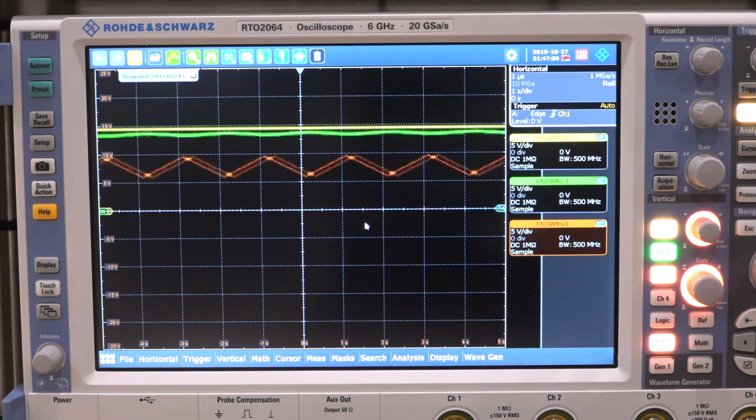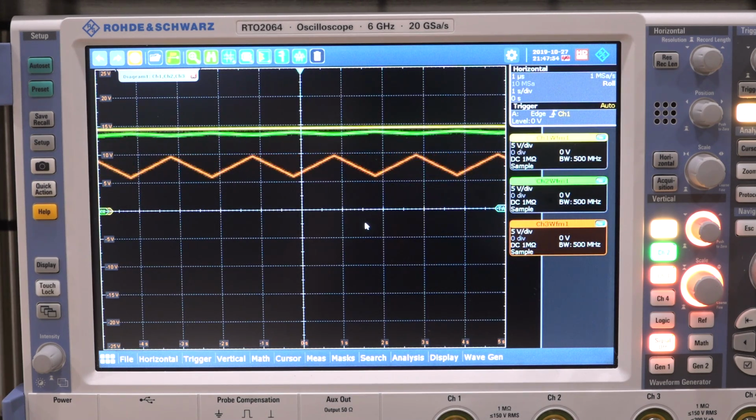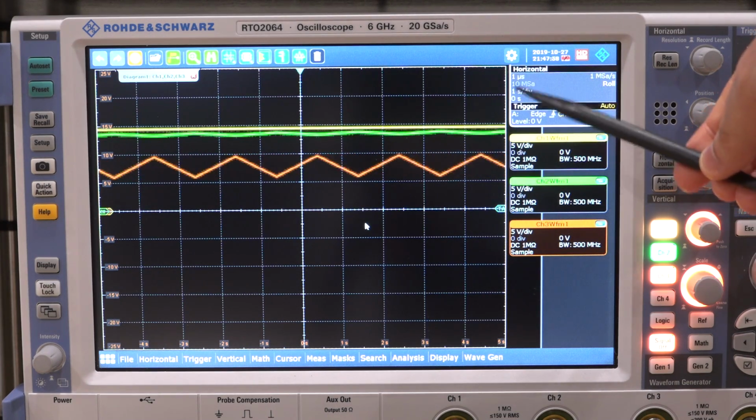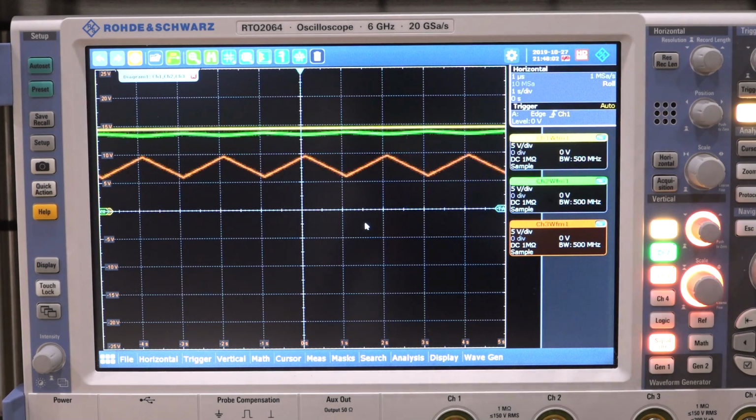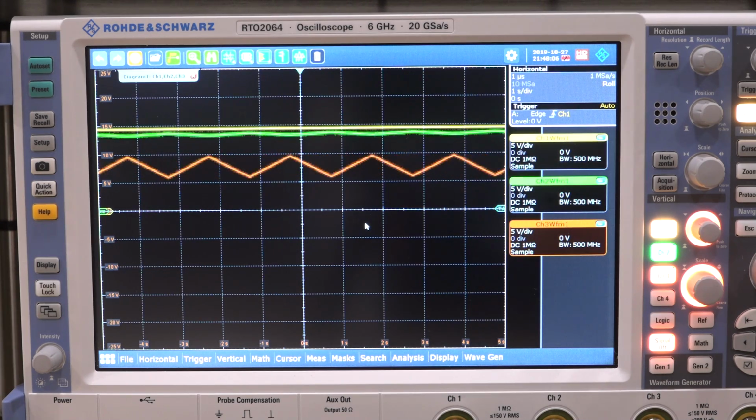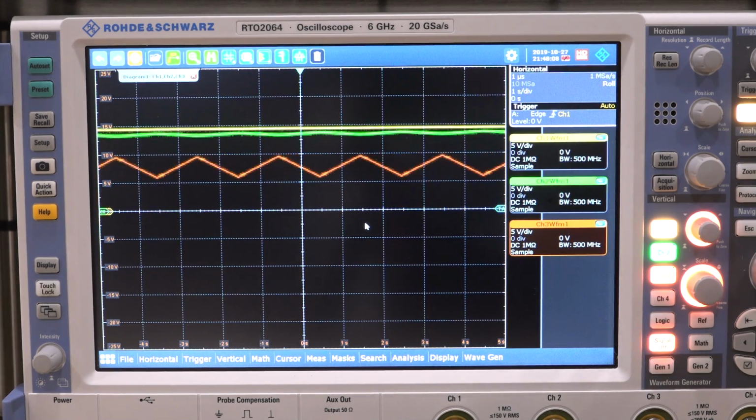The fact that it doesn't work across all frequencies is a bit of a mystery, but we're going to dig into that and see if we can figure it out. So I'm now fairly comfortable to go ahead and put some active probes directly on the line there and see if I can see any of those higher frequency components inside the PLL, and then we can tune it and see where it starts failing.